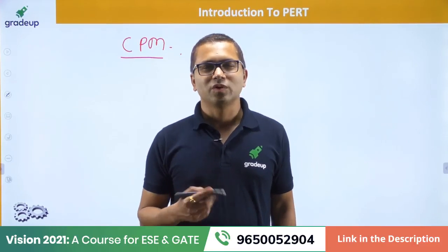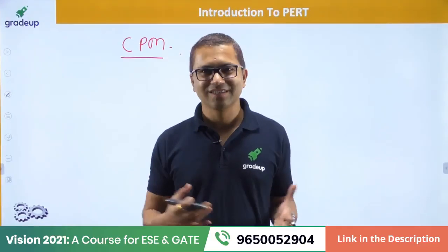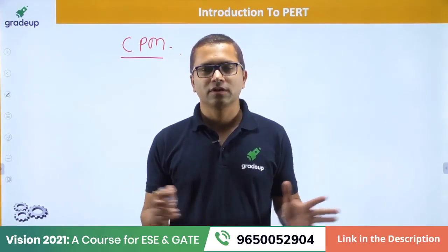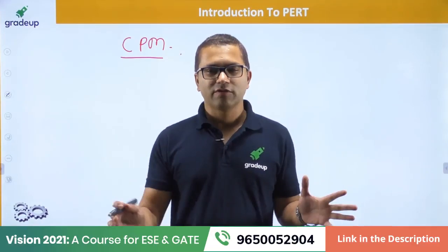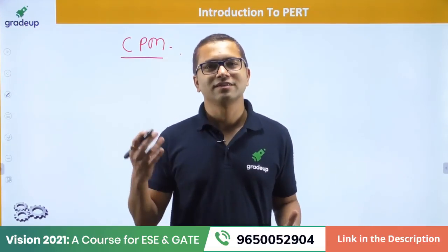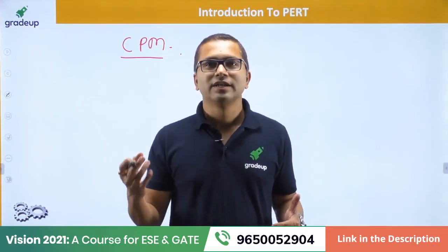What we did in CPM, I'm going to just recap for people who rush into this free course on YouTube. Firstly, we talked about various times: forward pass, backward pass, earliest start time, earliest finish time, latest start, latest finish time. And we also talked about float or slack.